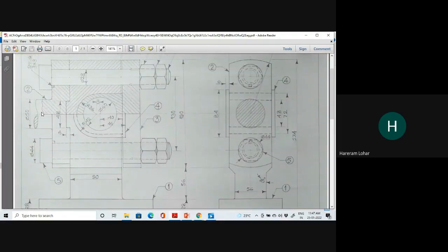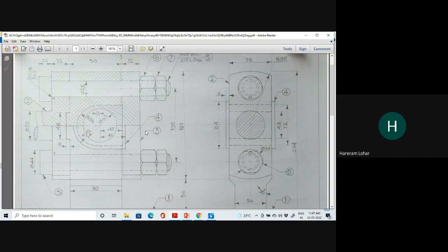So we are getting that. This one will be the piston rod end. Of course, here the cutout portion is there, and that portion will be hatched. Now when we see from that side, you will see the bolt head, which is circular, but again the nut will be there. The nut is a hidden object, so you have to go for the dashed line. The nut will be represented by a dashed line.